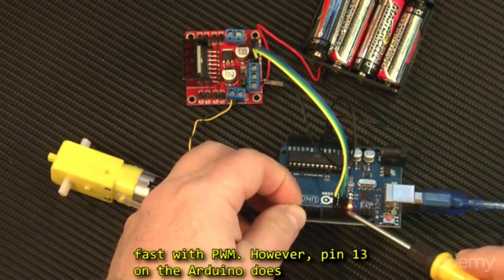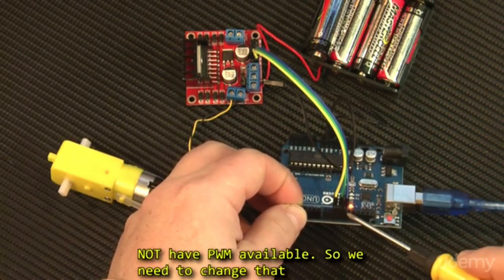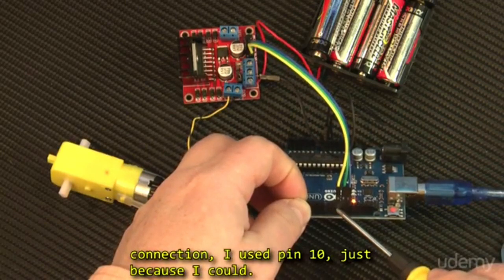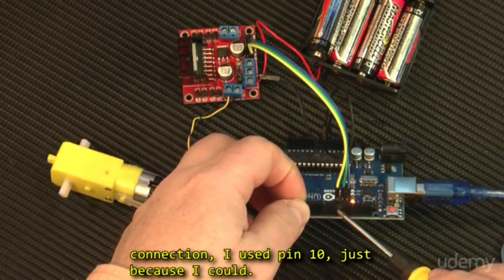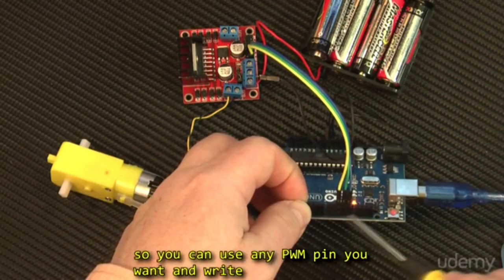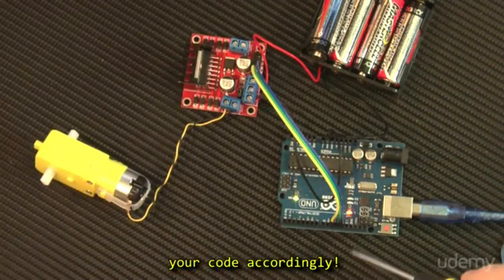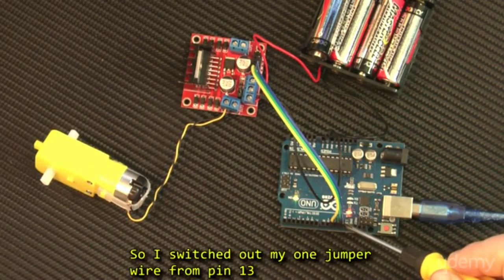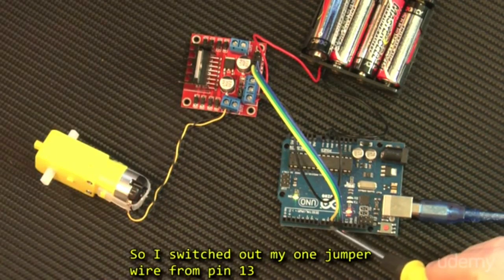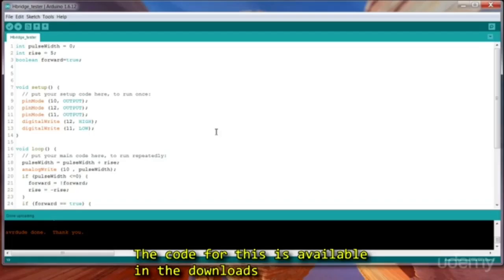However, pin 13 on the Arduino does not have PWM available. So we need to change that connection. I used pin 10 just because I could. You are a highly trained and qualified individual, so you can use any PWM pin you want and just write your code accordingly. So I switched my one jumper wire from pin 13 to pin 10. The code for this is available in the downloads section.